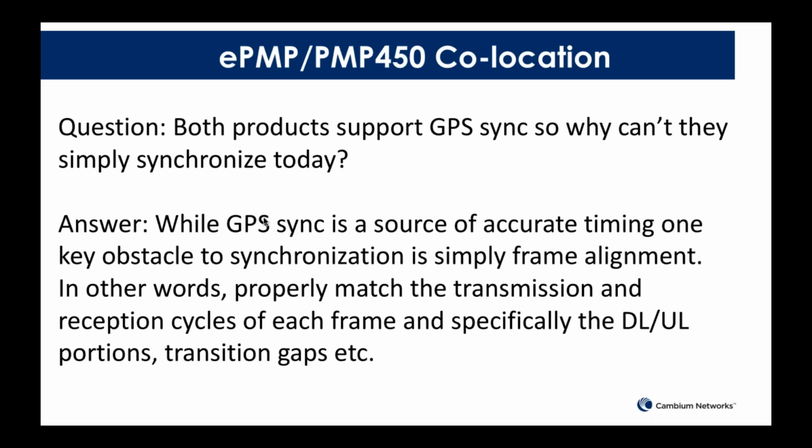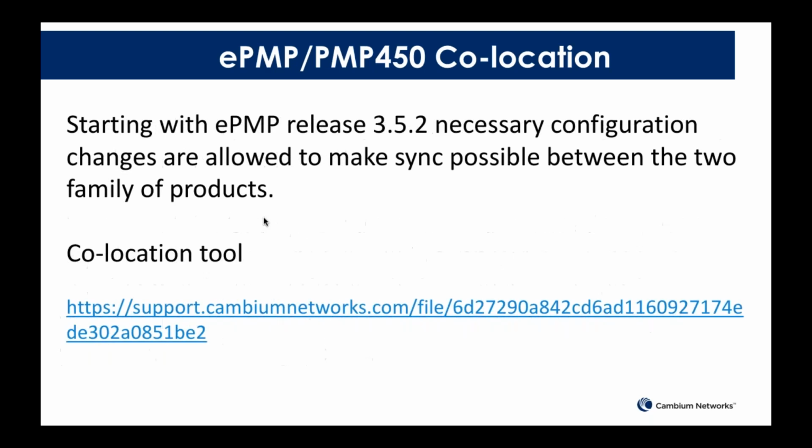So finally, in the 3.5.2 release of ePMP, we implemented this collocation scenario. Starting in 3.5.2, you can finally enable the collocation mode between CN Medusa, 450i, and ePMP. All the products from one company, from Cambium, can be collocated, and you can do the frequency reuse, have less self-interference, and use the frequency resource much more efficiently.